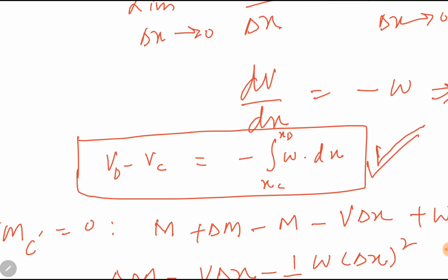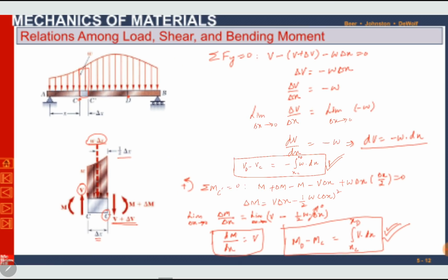W is distributed load. It is not for concentrated loads. Remember that whenever there is a concentrated force, shear force will be equal to the concentrated force, and it will remain constant between a concentrated force and a distributed force, or between two concentrated forces.